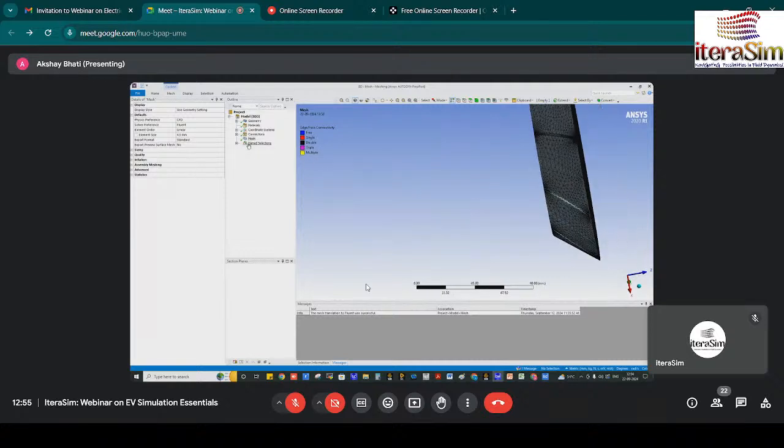And first, from the CFD point of view, you need to check the quality of the mesh in the mesh metric part. Actually, first I check the skewness. Mostly if skewness is beyond 0.9, your result would not be accurate, or otherwise the setup would fail after a few simulations. So first you need to check the skewness of the mesh, and 0.9 maximum, it should be below 1.